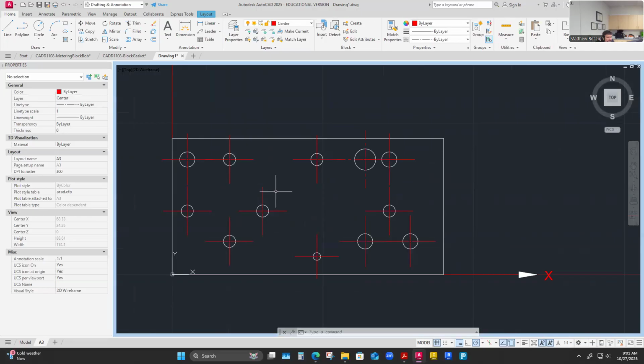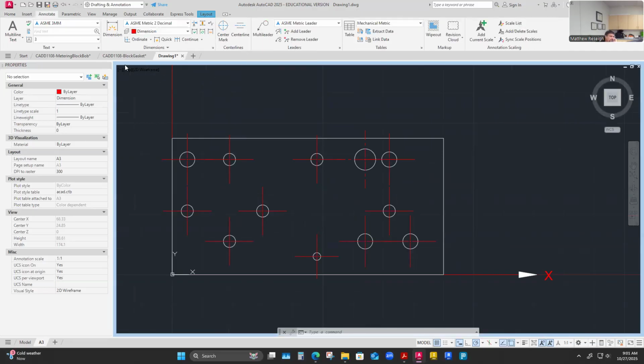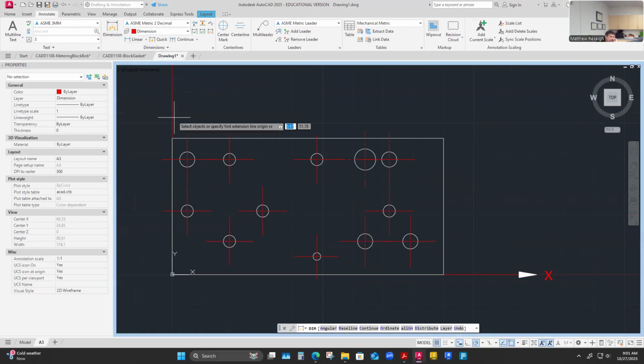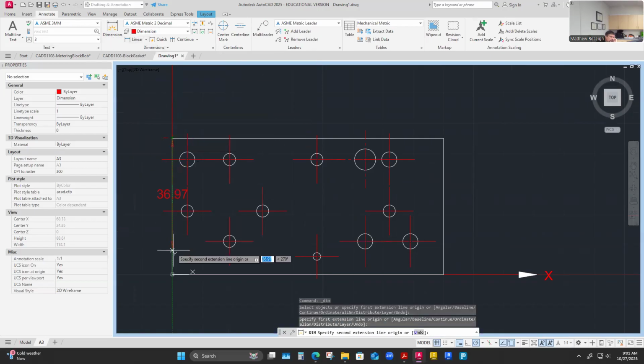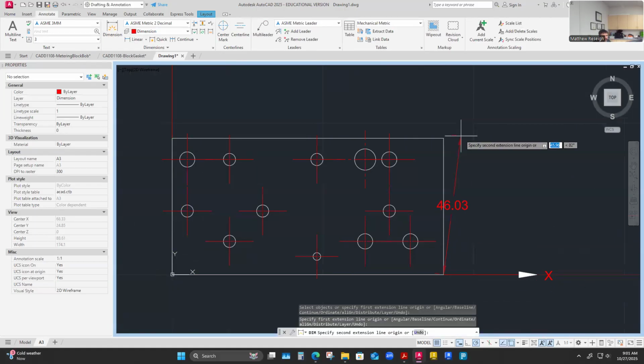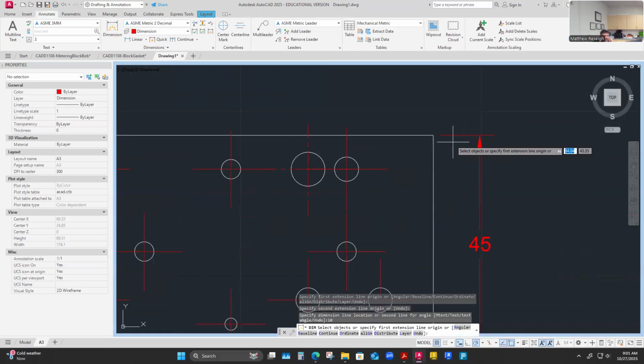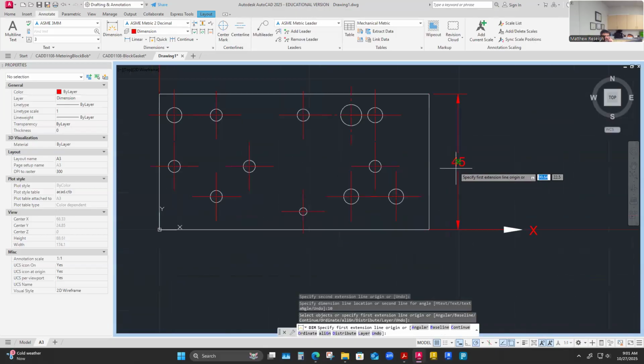And then what it also needs is some dimensions. I'm just not going to use the ordinate dimensions on these. I'm just going to use a linear dimension, or just my regular dimension here. If I want to know its overall height, then I could probably put this in between views. Sure, that would maybe be most correct, and maybe I didn't do that correctly on that first one, but when they go 10 millimeters over from the base is what would be correct spacing.